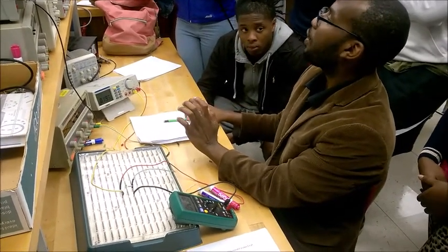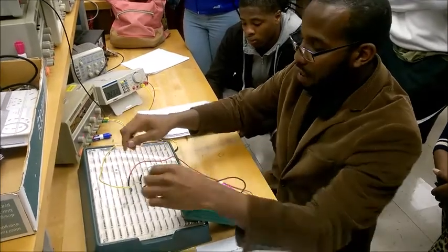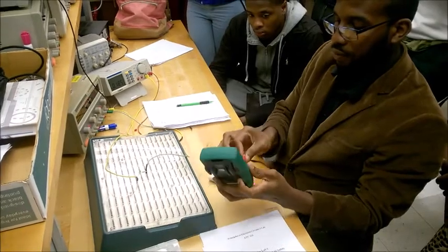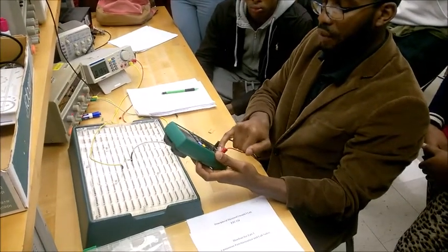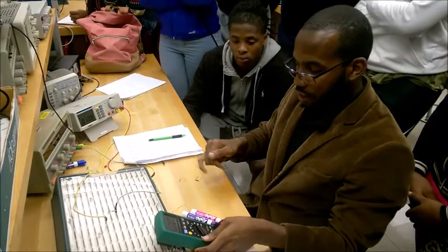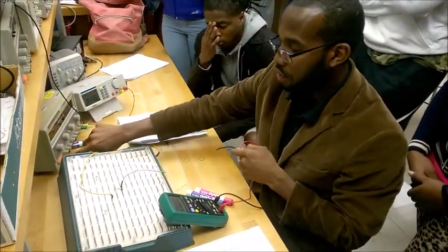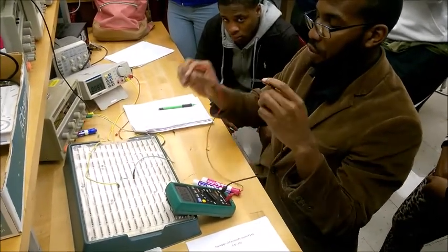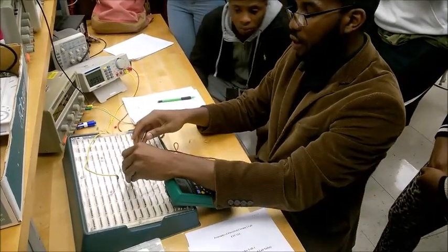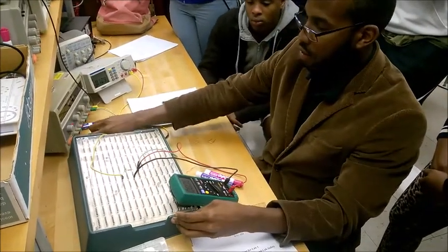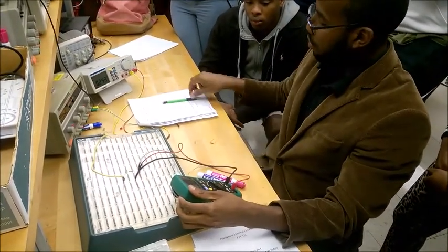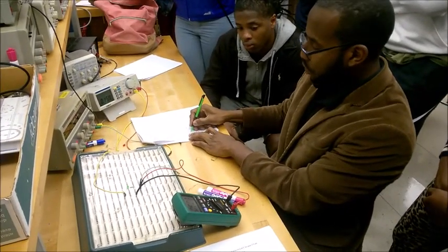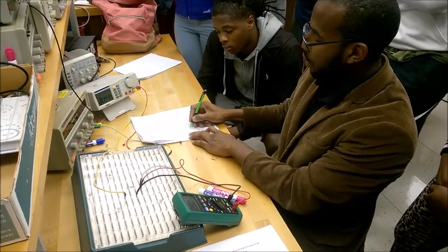The last one we need is the current. Like I said, I'm going to help you with the current. So like I said, with the current, we actually interrupt the circuit. So let me measure current here so you can see. So again, this is the milliamp port, and we have the milliamp setting here for current. And we actually want to interrupt the circuit and make this a jumper. So to do that, I'm going to put this right here, and I'm going to use this as a jumper to go from here to here. I'm going to turn this on. Alright, and now I get the current flowing through the circuit as 9.07 milliamps. Okay, thousandths of an ampere.